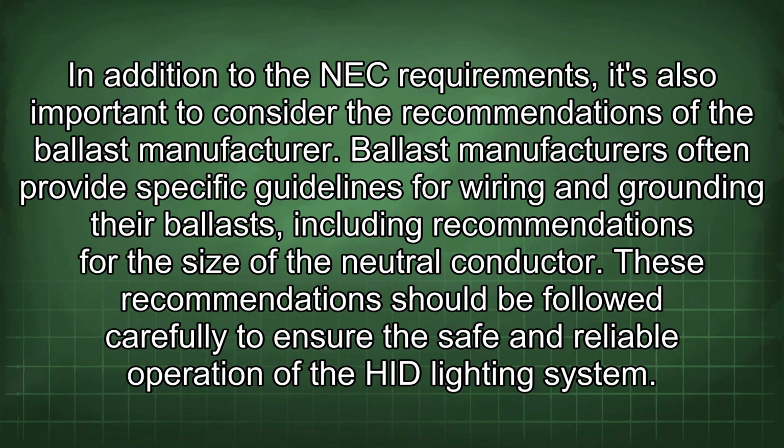In addition to the NEC requirements, it's also important to consider the recommendations of the ballast manufacturer. Ballast manufacturers often provide specific guidelines for wiring and grounding their ballasts, including recommendations for the size of the neutral conductor. These recommendations should be followed carefully to ensure the safe and reliable operation of the HID lighting system.